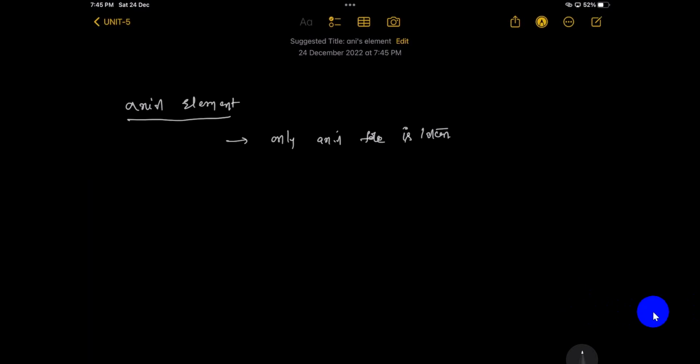See, in basic strength of materials, you already studied what axial force, axial stress, axial strain, and Young's modulus relations are. Just take one element. This is an axial element. Two nodes. This is element one, with two nodes. Only axial force is taken, no bending, no shear.